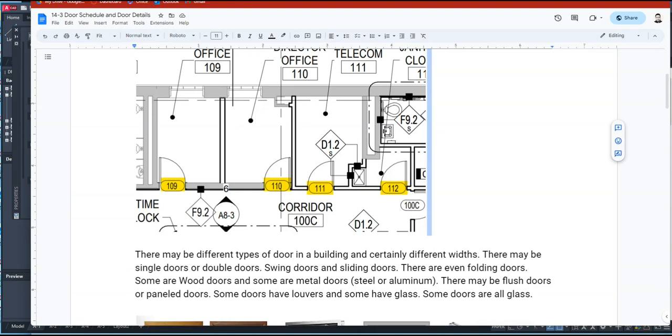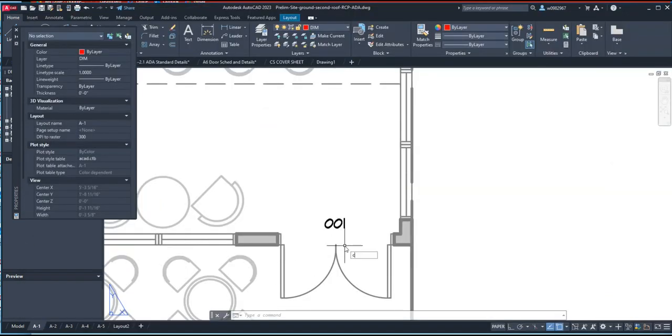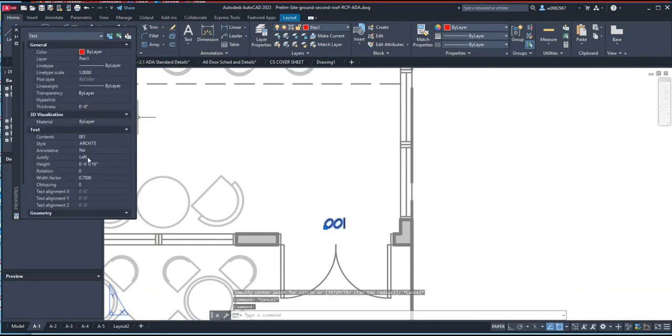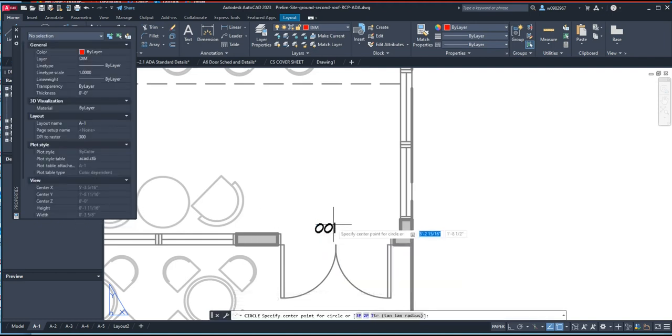We're going to do that by drawing a circle, and let's change this insertion first to middle center over here. There you go. So we can do a circle at the middle center, which is the insertion, at the same height, 3/32, for the radius. There you go. Then you can split this in half. We're going to do a break from here to the quadrant.